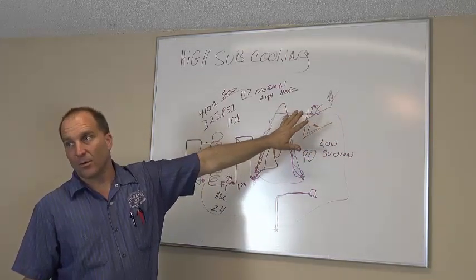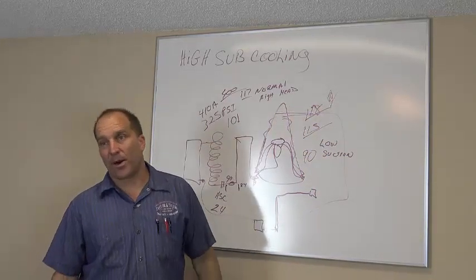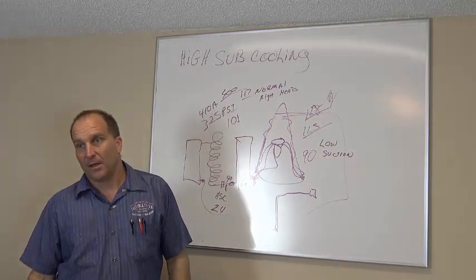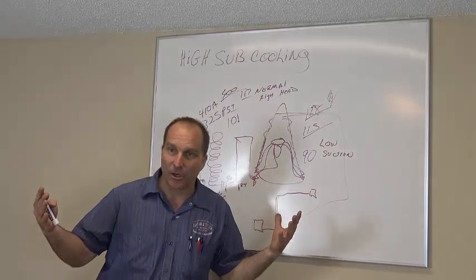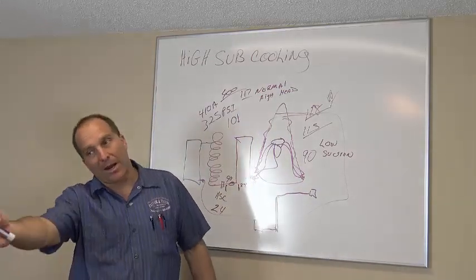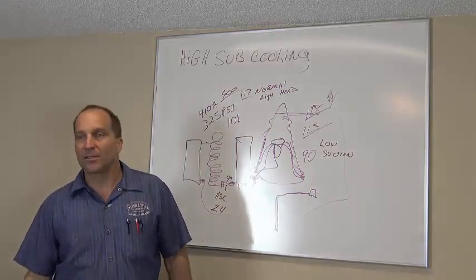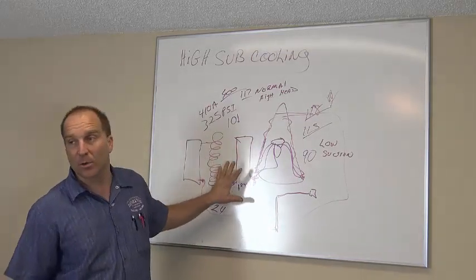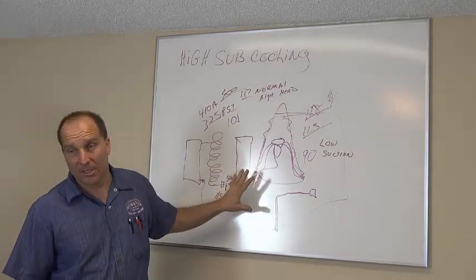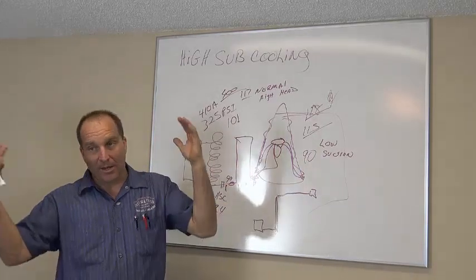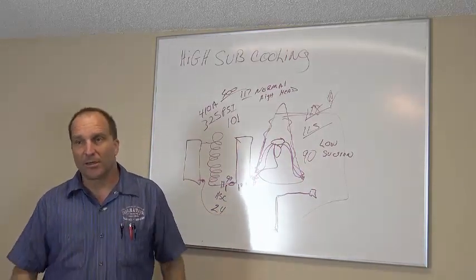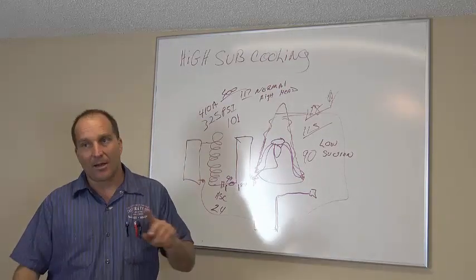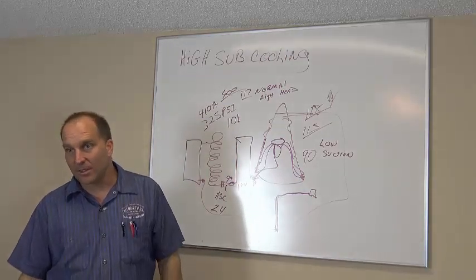So your system's not charged properly now, is it? So now you have to start looking at your high superheat chart. And you go, okay, I'm going to go to my high superheat chart. What causes the high superheat? I've got a normal subcooling, right? I've just got high superheat. So we go down the whole chart. This is all the stuff that causes the high superheat. Restriction in the TXV, kink in a line, whatever, okay? High heat load, all this kind of stuff.